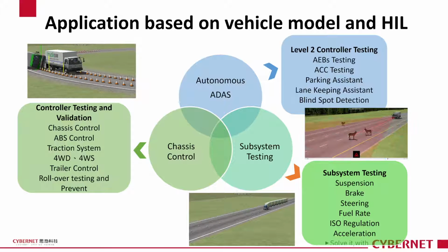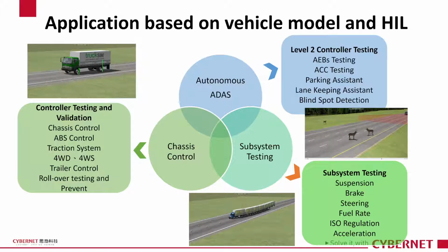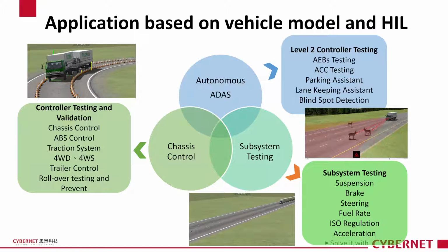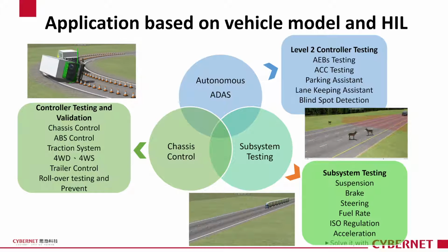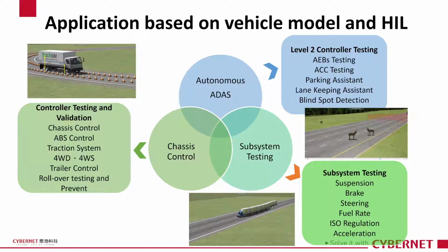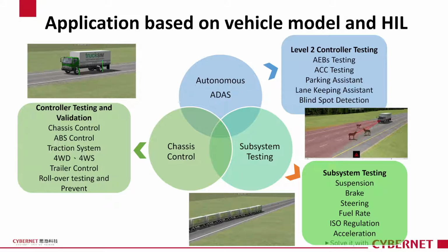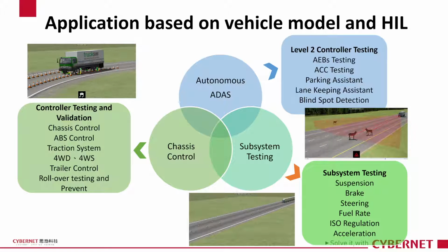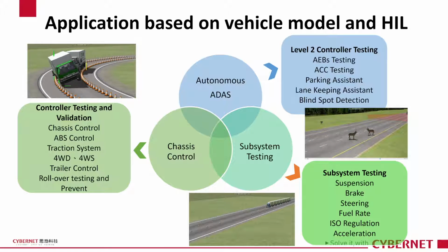We can also use simulation tools to do subsystem testing. Sometimes we will want to evaluate different subcomponents on the same car. For example, which brake system is suitable for my target? We could build different brake systems in CarSim and test them with the same car.